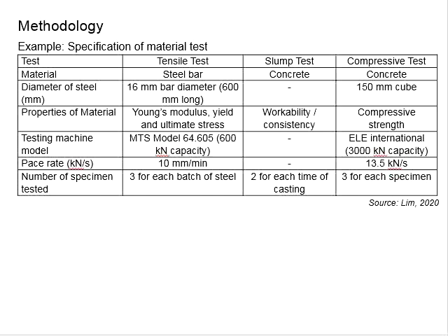Therefore, whenever you want to test a sample, you can actually roughly calculate the anticipated capacity, which in the case of the steel bar, you know that the grade of the steel bar Fy equals 500 megapascal, and you will expect that Fu is going to be about 30% to 40% higher than the Fy.